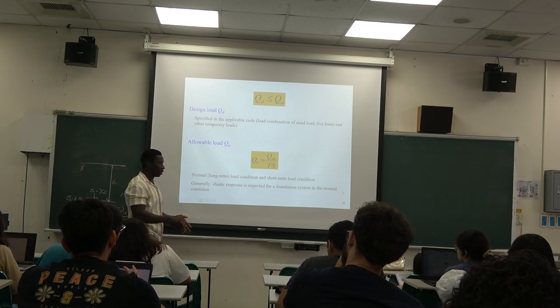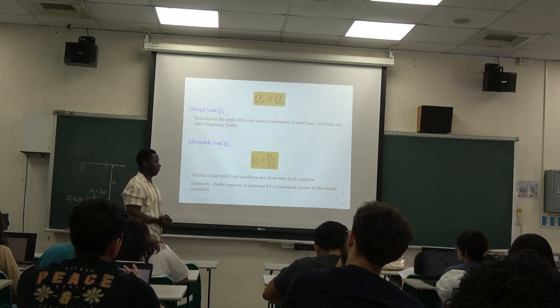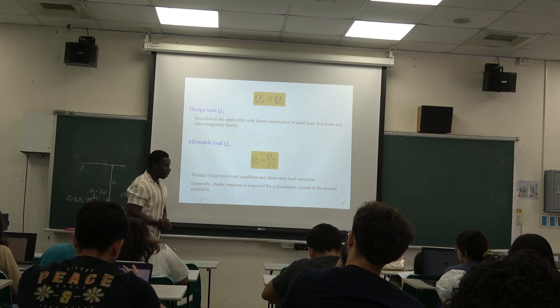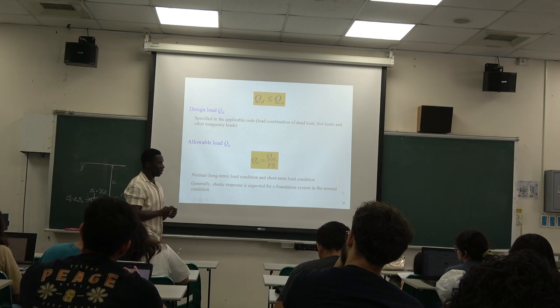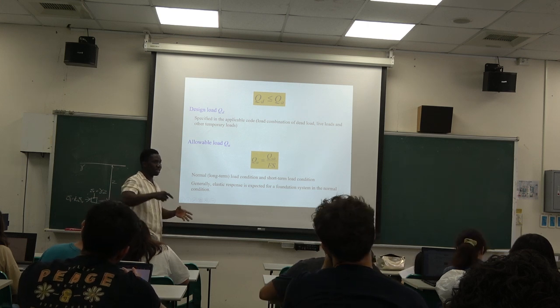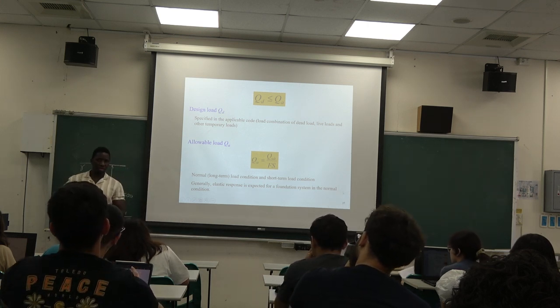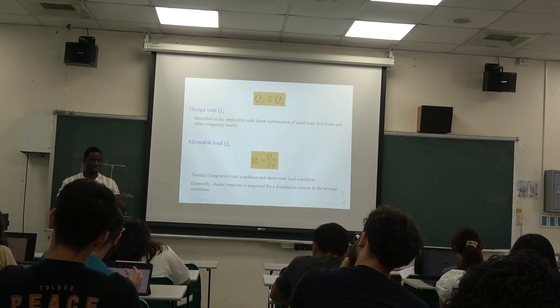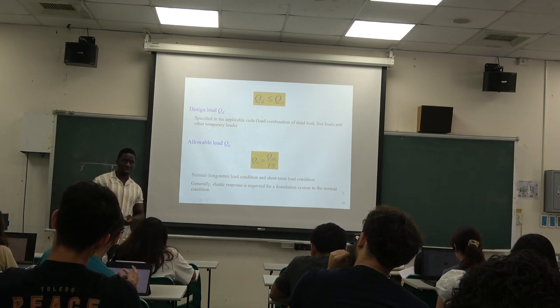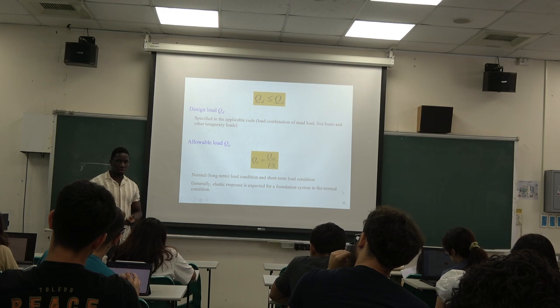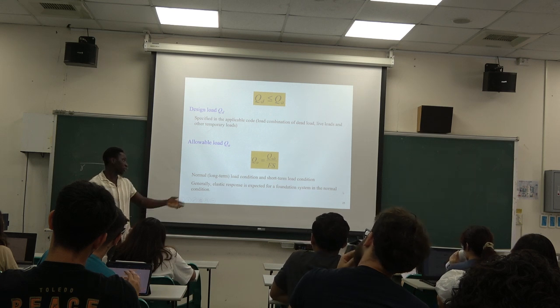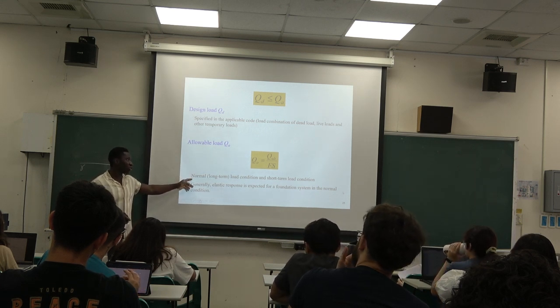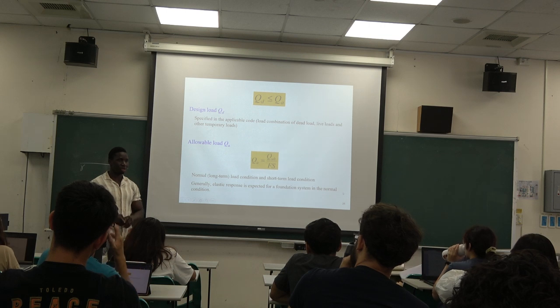When you just put the loading onto it, for example, when we are talking about clay, we might do the undrained analysis for short term, but in the long term you might consider consolidation, right? Because the loading is on it. Over time, it might cause the water pressure to dissipate, but that takes a lot of time. It doesn't happen immediately. So that's why sometimes we consider the long-term load condition and the short-term load condition.